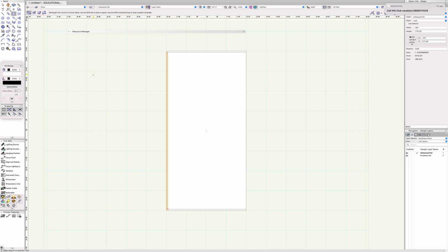Now I can select this one, as this is already selected, and select mirror, and then again bring it onto the center as the mirroring plane. Now I have mirrored this toggle onto the right-hand side. So now I do have top, bottom, right, and left toggles. These four toggles I do have.